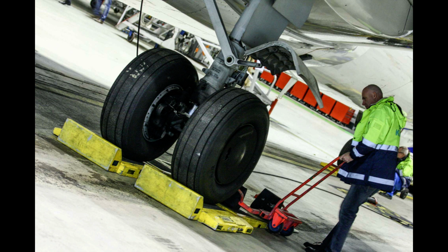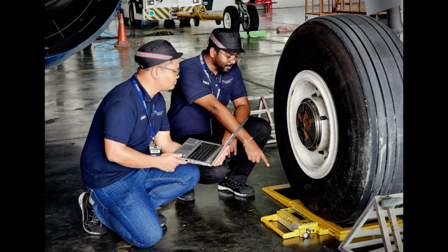Overloading of the aircraft is not the only concern, the distribution of the weight is important also. The aircraft has CG limits, and any loading that places the CG outside the established limits seriously impairs controllability of the aircraft. Weight and balance is of such vital importance that each Federal Aviation Administration, FAA, certificated mechanic or repairman maintaining an aircraft must be fully aware of his or her responsibility to provide the pilot with current and accurate information for the actual weight of the aircraft and the location of the CG.